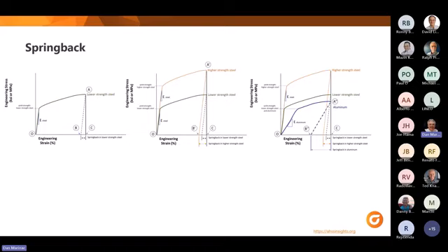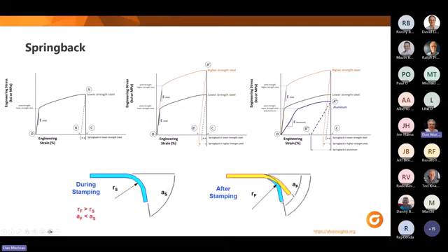And it's significant to note this, because if you try to change your designs from steel to aluminum, especially with the advent of electric vehicles demanding aluminum and lighter weight materials these days, realize that you're going to have a much larger issue with springback. So, simple springback. If we take just a simple bend over a radius, we see that we can only induce so much force, but after we've induced it, depending on the material, it will spring back to this yellow state right here.